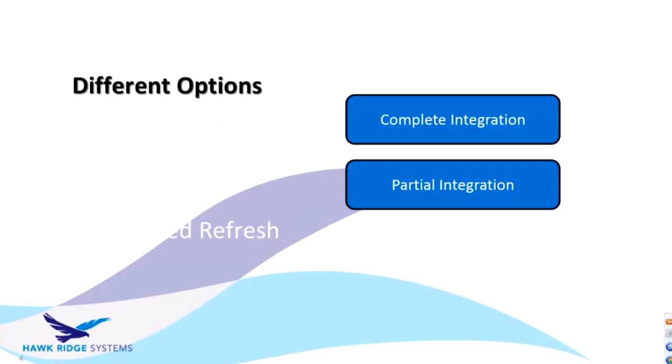as they would before. So the key thing is that EPDM will automatically check toolbox parts out and in as needed so that the latest versions are used. It also adds missing toolbox parts to the vault, redirects assembly references to the toolbox parts within your vault, and also it supports the use of the option within toolbox to create new parts within the vault.